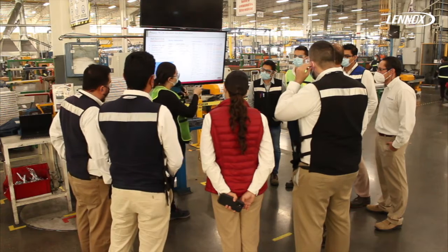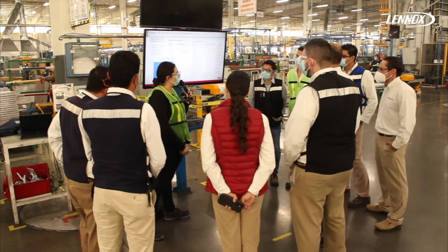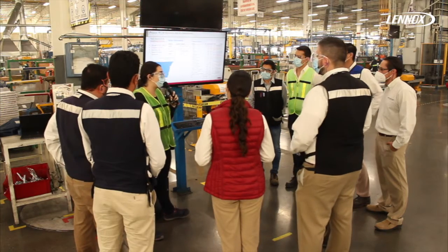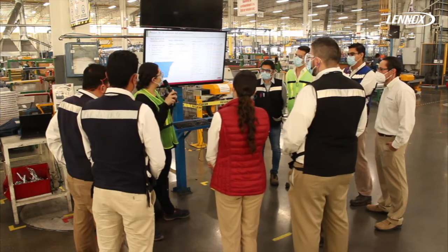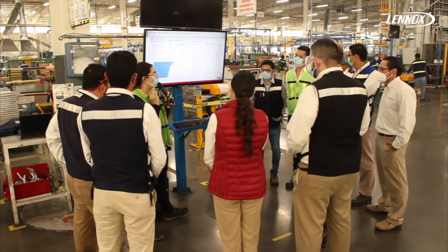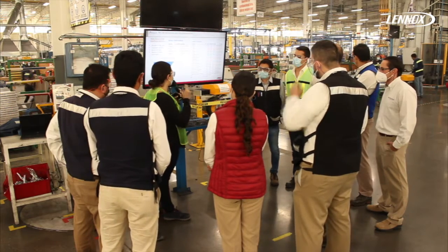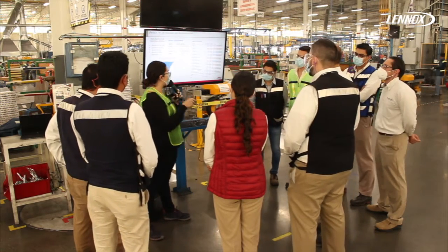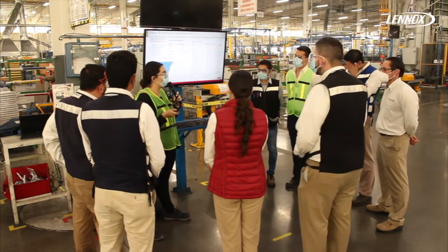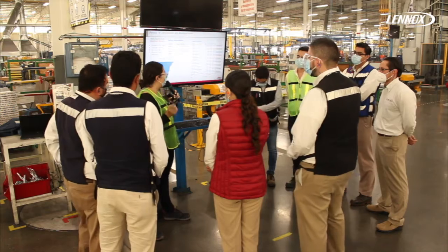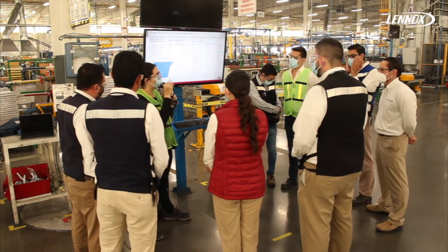This is all of the data that we got from Minitab, and as you can see, our p-value is lower than our significance value, which is 0.05. That tells us that all of our factors and their interactions are very important in our process, and we should take them into account. We should solve them so we can have 0 leaks. Here we can see that the main factor is the insertion heat. It has to have it in order not to have a leak, followed by the interaction between the height and the insertion heat and all of the other factors.